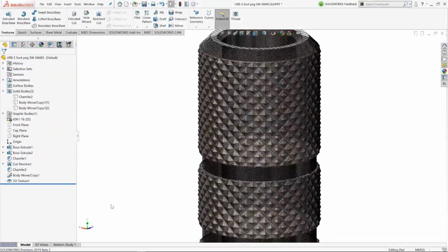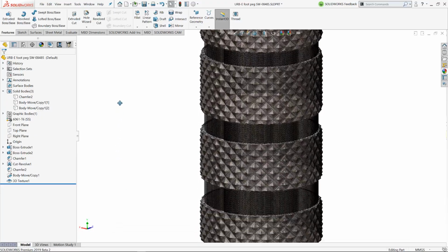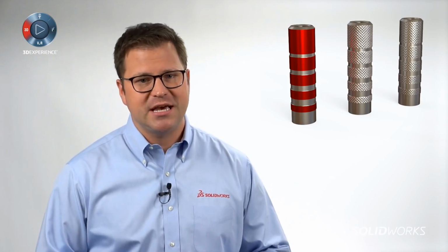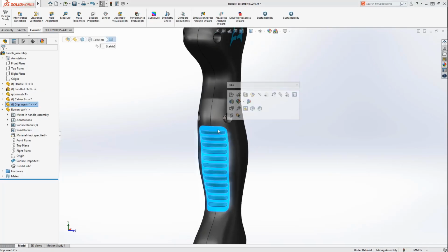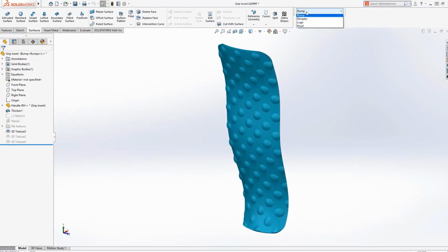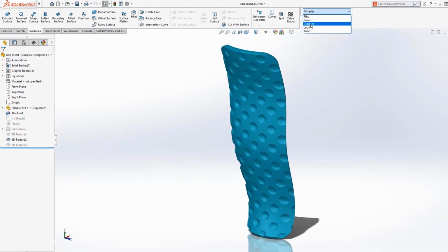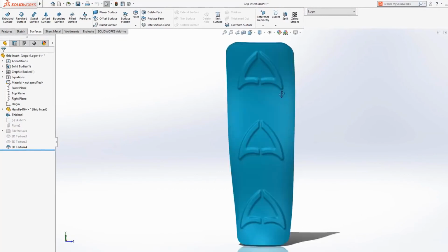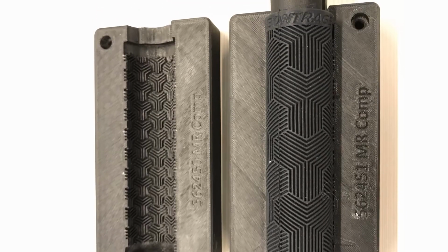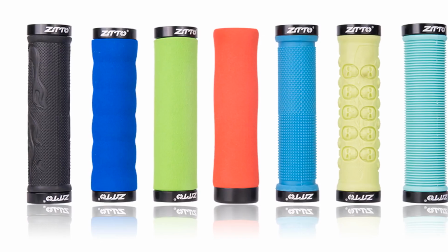This is much faster than parametric modeling of the knurling, which is overkill, especially in the prototype phase. In the concept phase, 3D texture is a shortcut for generating a variety of textures and geometry. Common use cases could include grips, complex patterns, aesthetic surfaces, really anything with texture or something that's just too complex to model in the beginning. I can use this resulting body directly for 3D printing.